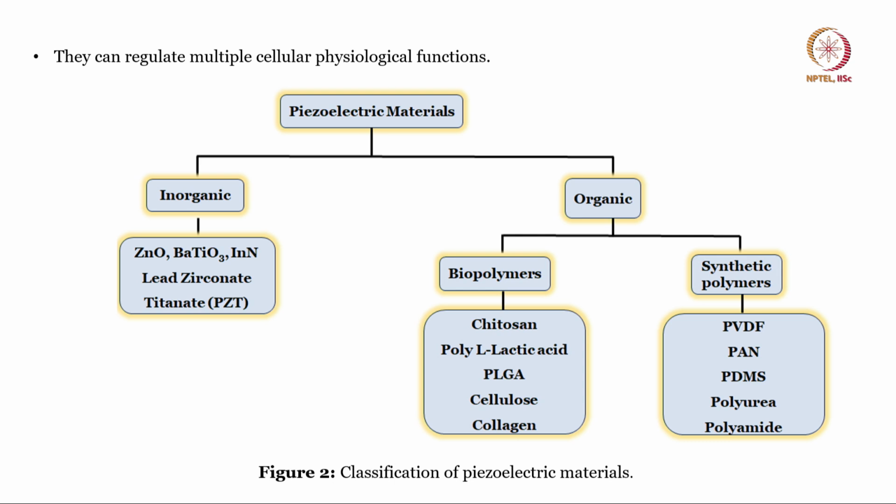Next, coming to the classification of these piezoelectric materials. These piezoelectric materials are broadly categorized into inorganic piezoelectric materials and organic piezoelectric materials. If we come to the inorganic piezoelectric materials, as the name itself says, these are derived from inorganic materials such as some ions, sodium, potassium, like that. So those inorganic counterparts will be present in these inorganic piezoelectric materials, and the best examples we can quote here are zinc oxide, barium titanate, indium nitride, lead zirconate titanate, gallium nitride etc.